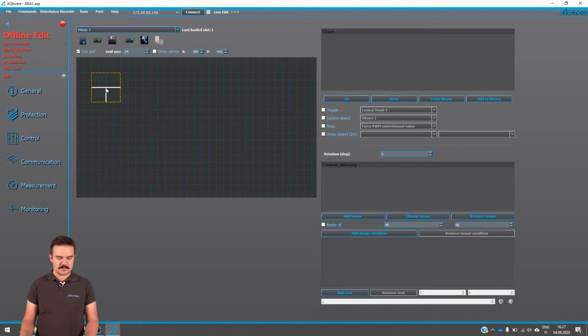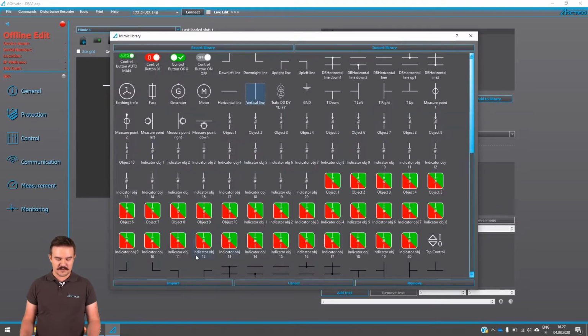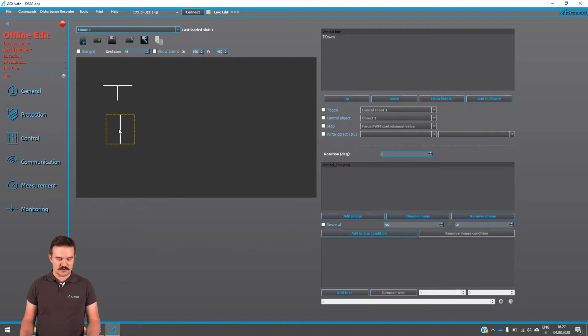If I divide that 48 with 2, I will get a little bit smaller increments, or you can add whatever you want there. Or if you want to move the items freely, you just disable the grid and then just move it freely. But then it might be a little bit difficult to align some of the items together, as you might see here.